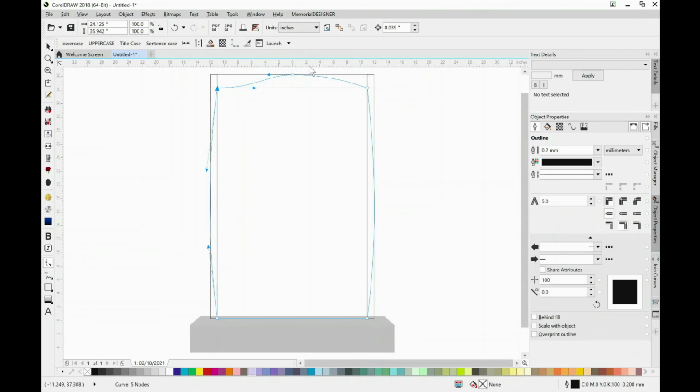But I want to make sure that this OG is symmetrical. So the way that I do that is I want to put these lines here at a known position. And so what I do is I actually take my rectangle, which was my drop, slide that in. By pressing the shift key, it will mirror both sides exactly the same. Slide that in, and now when I go back to the pick tool and select my line here, I can move that and put it on that node. And if I move this arrow and put it on that node, then I know that this OG shape here is completely symmetrical.